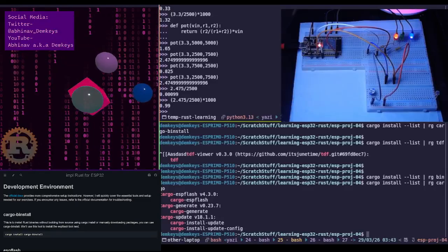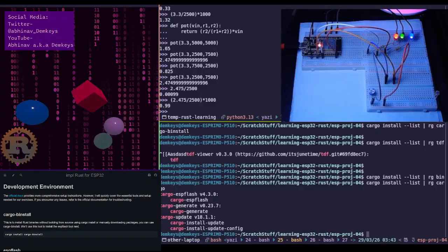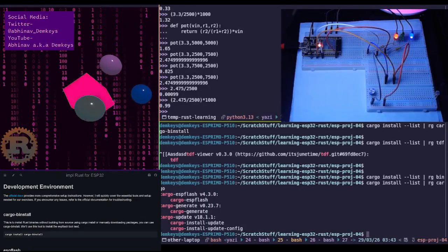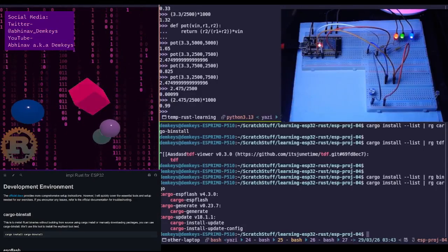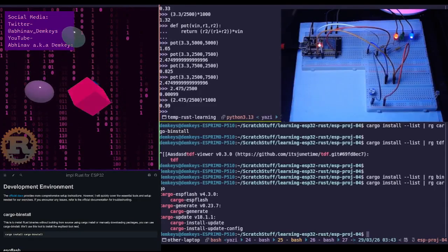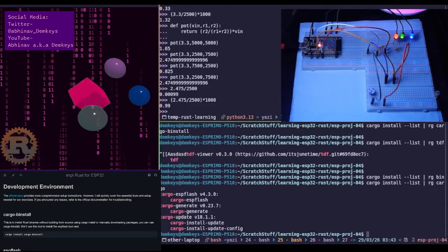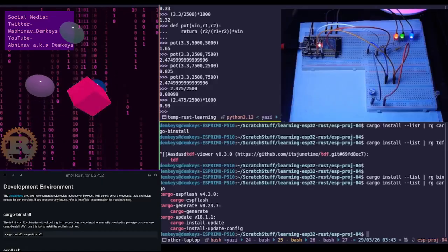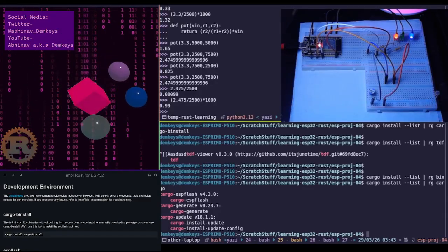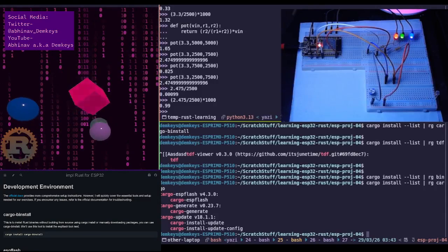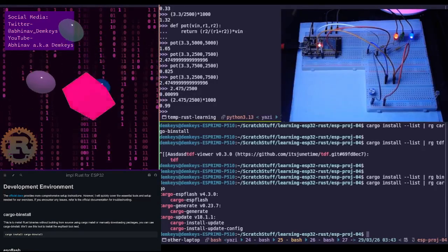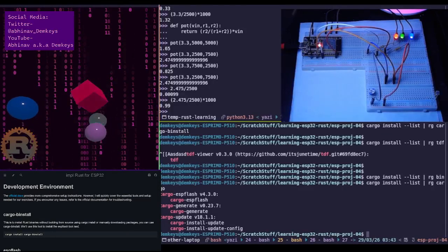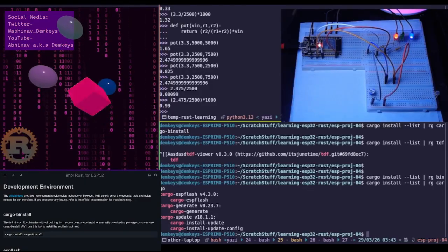Let me explain what a relay helps with. Then I'll talk about the module. The relay itself is used to allow you to basically create a sort of switch in between. So think of it as an electronic switch, but what's happening is that you give the relay a small signal on one of the pins, and based on that signal, it trips some kind of switch internally.